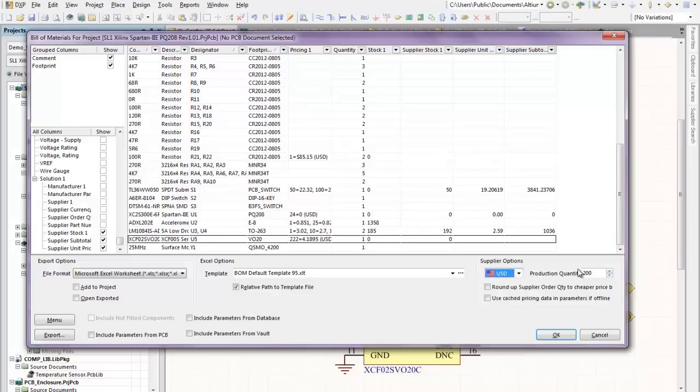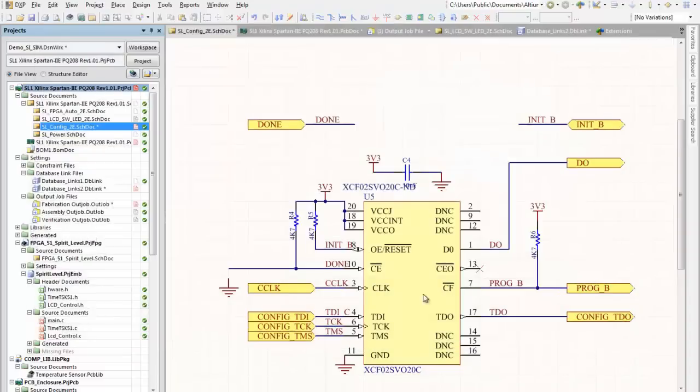You can see I can choose that currency. Maybe I want to make a run of 400 of these. It will subtotal that exact amount for that component. In this case, it's $1,675.80. And I can pass that bill of materials off to my procurement department. They can then begin either looking at lead times to get the stock in place, or maybe I want to just replace the component completely. I can identify that quickly through that bill of materials that is reported in Altium Designer.